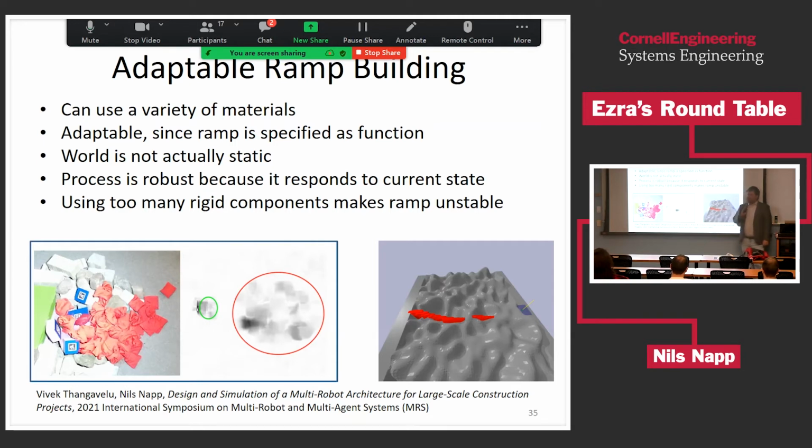Indirect communication is limited, and consistent observations are actually a problem, right? Because to do this centrally, I would need a global, consistent estimate of all the terrain. That's kind of easy to do in a lab with a Vicon system or 3D scanner, but it's pretty hard to replicate. And each robot, even if they can all communicate, would potentially have slightly different views of the world based on their own sensor readings. And fusing that in a consistent way is not trivial.